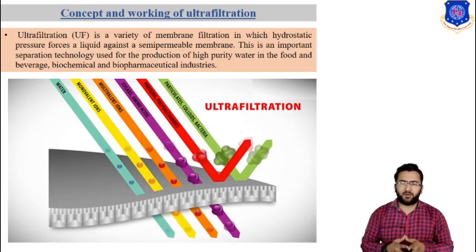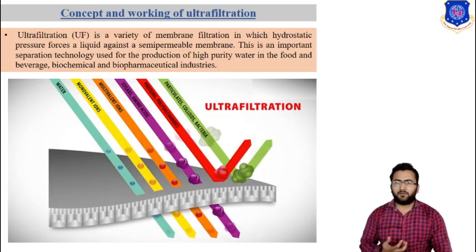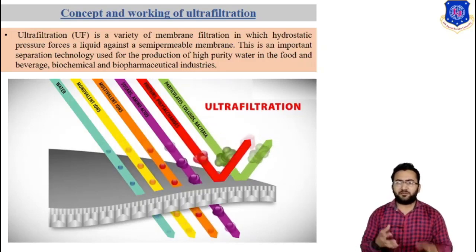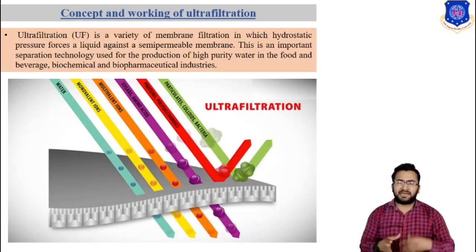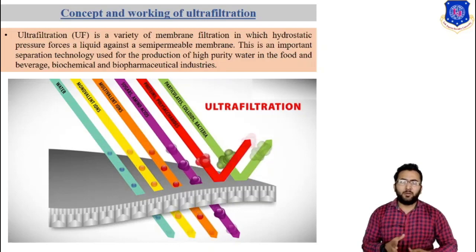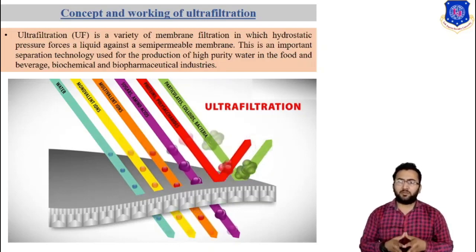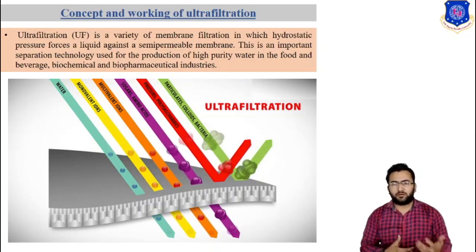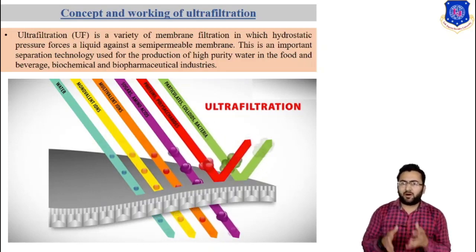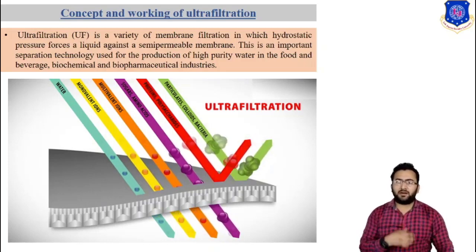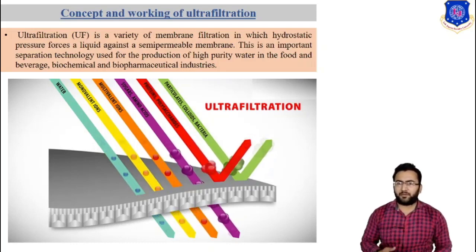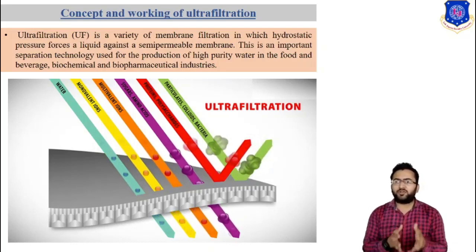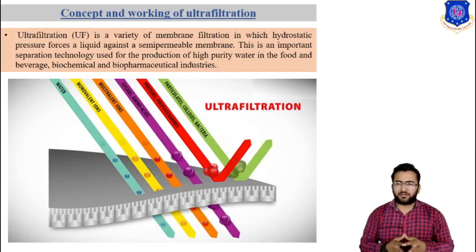The membrane module material must be compatible with chemicals such as hydrogen peroxide used in sanitizing the membrane on a periodic basis. Inorganic materials such as ceramic, carbon-based and zirconium-based membranes have also been commercialized by several vendors for ultrafiltration membranes. So there are various modules used in ultrafiltration.